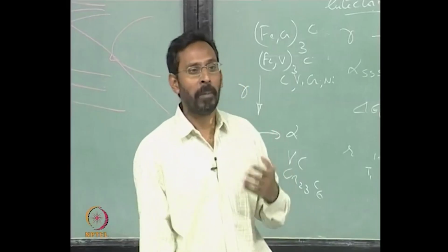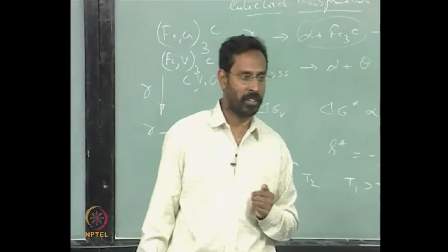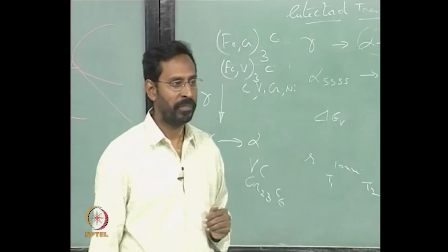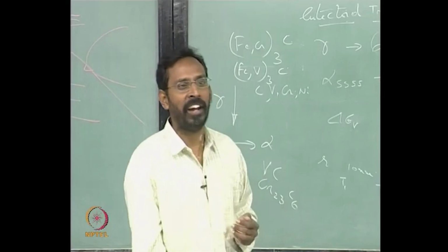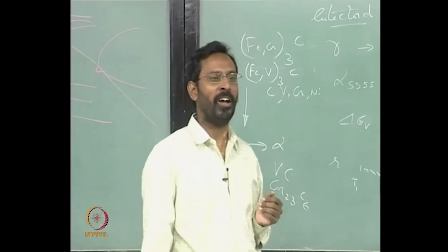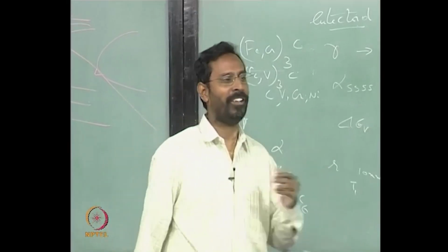People also use this in powder metallurgy components many times for what is called self lubrication. You add lead in leaded bronzes. Why is lead added? They are all bearing materials, bearing alloys. In bearing alloys you deliberately add lead because lead is soft.